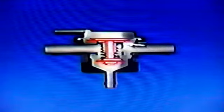If this diaphragm were to rupture, the control valve would cease to operate and we'd be sending fuel vapors into the manifold. To prevent this, all you have to do is pinch off and/or disconnect these lines so that no fuel vapors can get into the engine.